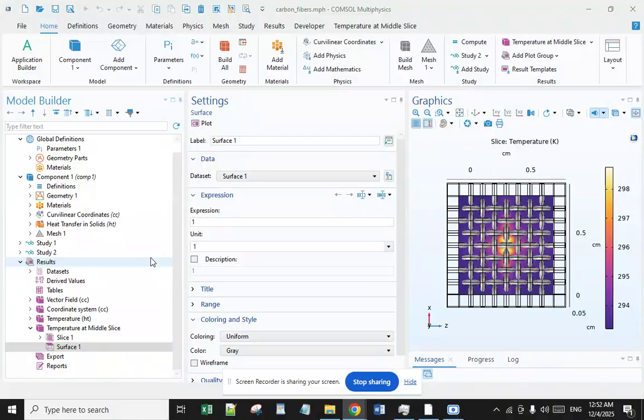While it is expected that the fabric is uncompressed in the measurement of the longitudinal conductivity, it is compressed in the measurement of the transverse conductivity. The fabric volume fraction is also calculated from its density, considering that it consists of carbon fiber, ignoring the stitch and binder mass, with a density of 1760 kilograms per cubic metre.